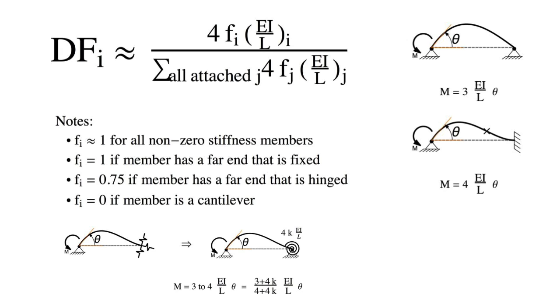We assume the spring stiffness to be approximately 4EI over L, which is the stiffness if the other end is fixed. Based on previous discussions, a value of 3.6EI over L would give slightly better results, but we will ignore this and just use the simpler estimate.